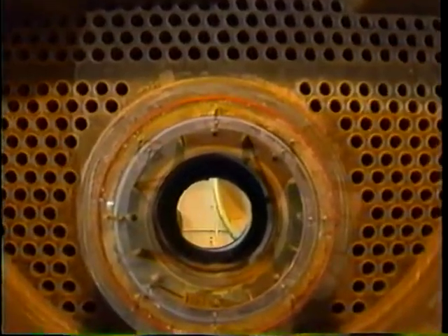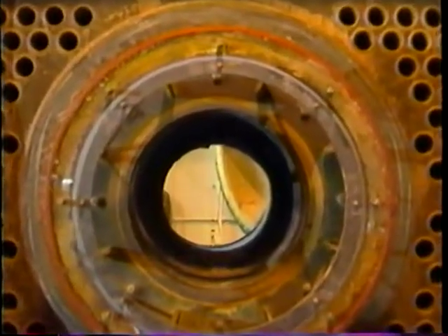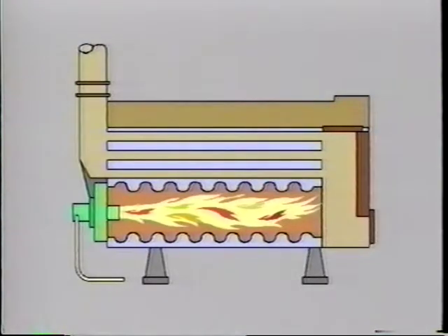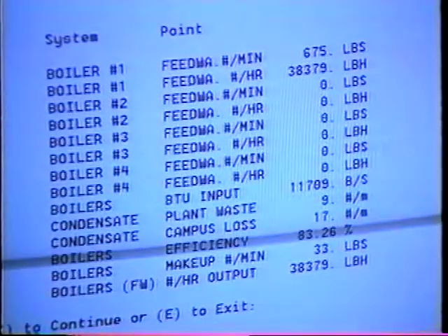Heating surface is the surface in which heat from the gases of combustion is transferred to the water in the boiler. A larger heating surface results in more heat transferred to produce increased water circulation and faster formation of steam bubbles. This results in greater thermal efficiency of the boiler.